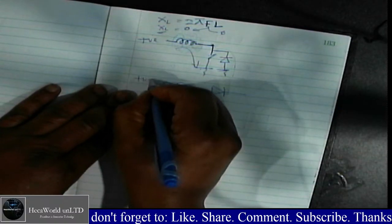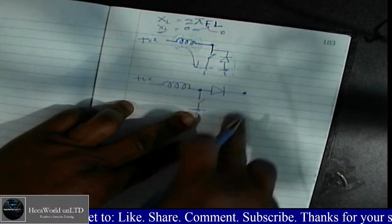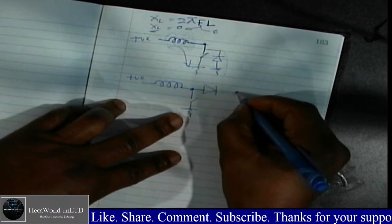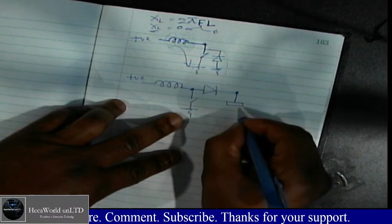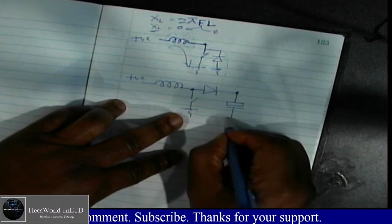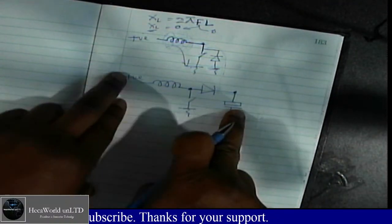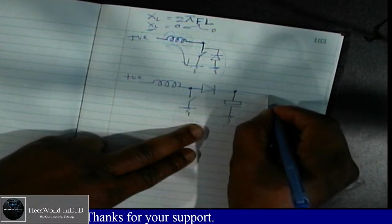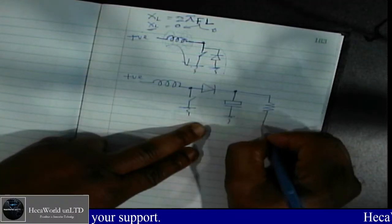Here I'll put my positive voltage, and here, because I need to make this portion, the output circuit, useful, I'm going to put a capacitor for filtering, a filtering capacitor here. Ensure that the voltage rating of the capacitor can handle the voltage that is going to come in here. And then I'm going to have my load. So I'm just going to represent my load with a resistor.